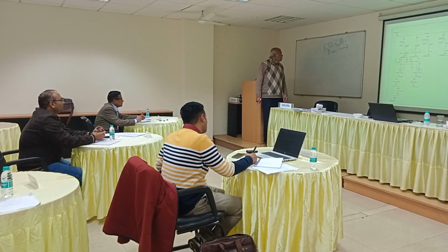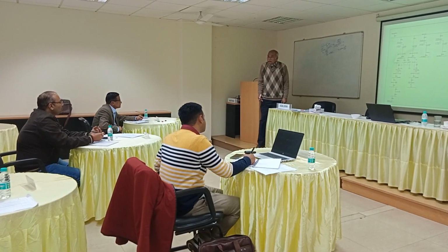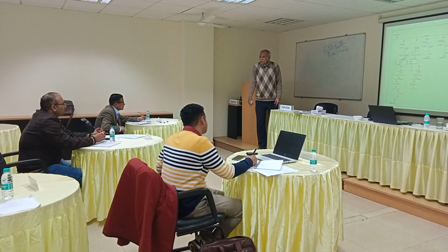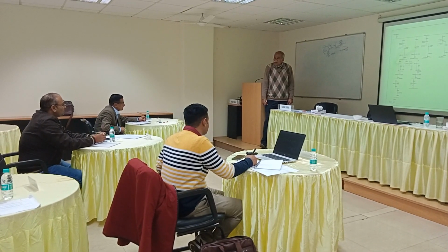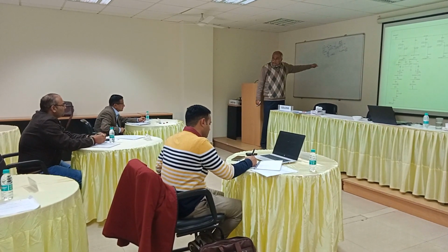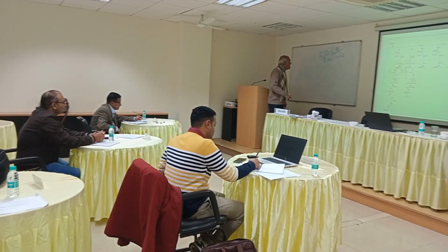ZT, you see, 7% of the ohmic value. How are you getting the ohmic value? kV square by MVA, the same way.